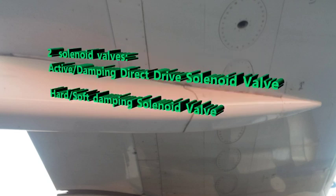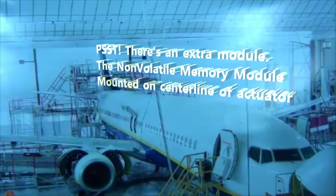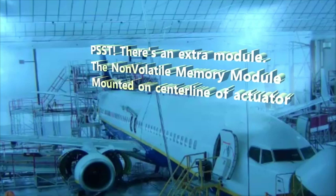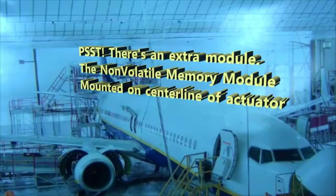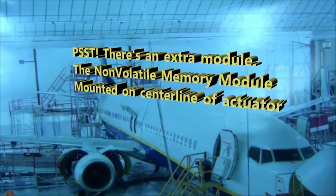There are 2 solenoid valves with this: the active and damping mode direct drive solenoid valve, and then you have your hard soft damping solenoid valve. Those are the 2 existing there. There is also another module, actually mounted on the center line of the actuator itself, and that's your non-volatile memory.